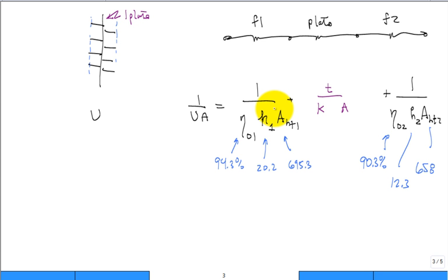So it accounts for all of those passages on both sides. So what you're going to do is take the area of one plate, multiply by the number of passages, and multiply by 2. Make sense?